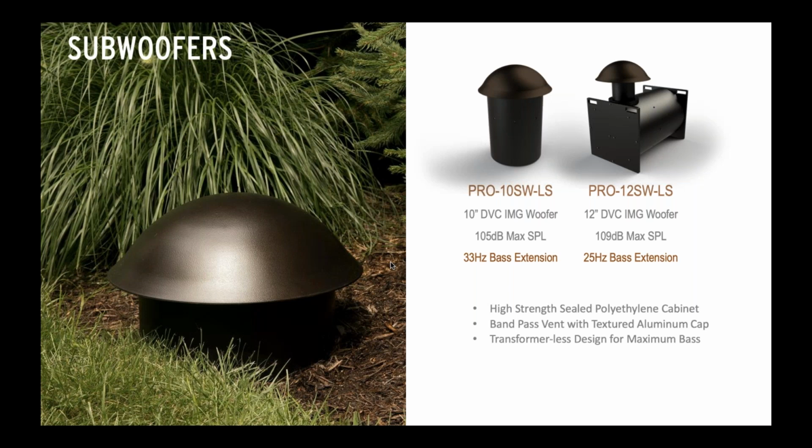So in a 16 ohm load, just from Ohm's law, you're getting about 250 watts to each of those subwoofers. Now, the subwoofer doesn't care if it has a transformer or not. The subwoofer cares about wattage draw, and the amplifier cares about impedance, right? So a 70-volt amplifier is just fine with a 16 ohm impedance. The subwoofer is just fine with its 250 watts of input. So everything's hunky-dory from an install standpoint, from an electronic standpoint, but we don't have the transformer saturation that you typically see with 70-volt subwoofers.